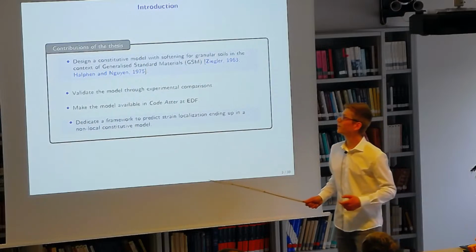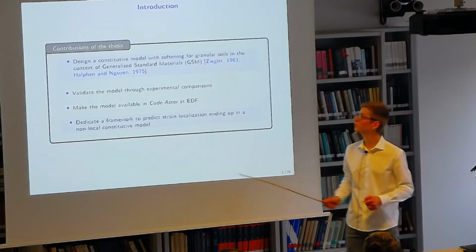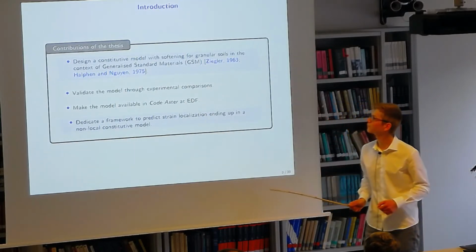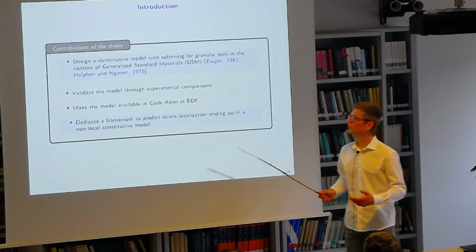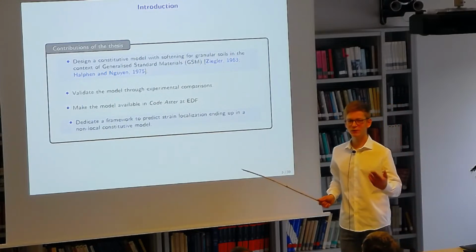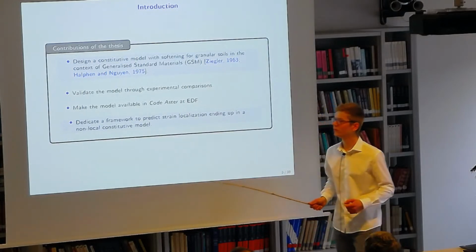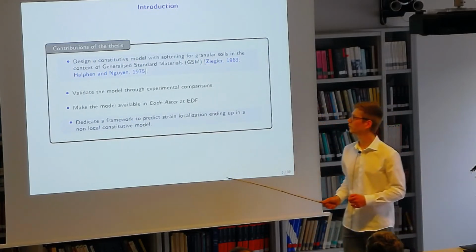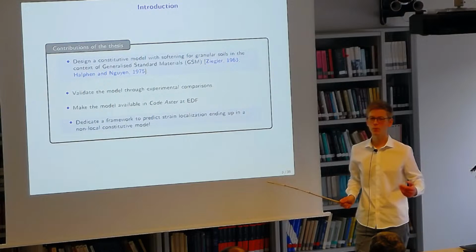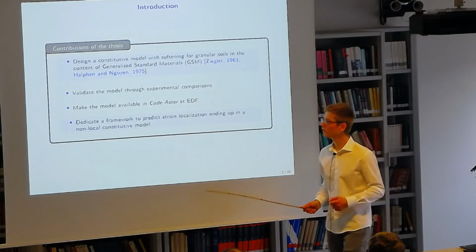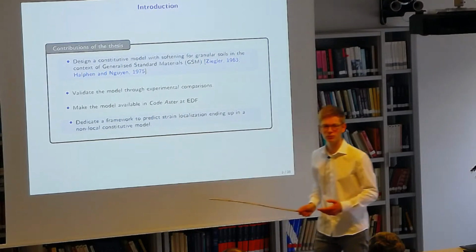We thus contributed by designing a constitutive model for granular soils which is thermodynamics-based, in the context of generalized standard materials. At the same time, the model was validated with experimental data in order, in parallel, to propose a methodology of calibration for the parameters involved. The model has finally been made available in the finite element software Code_Aster used at EDF. A final contribution was to develop a framework to predict both regimes with strain localization and softening for the constitutive model. In this presentation, I will focus on the first and the fourth of these contributions.